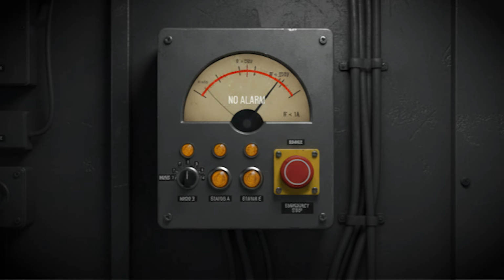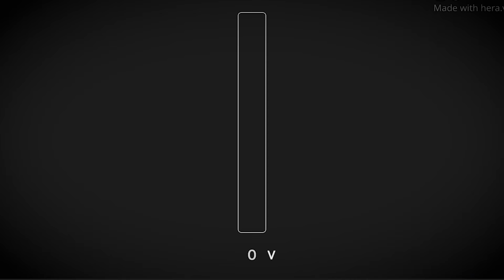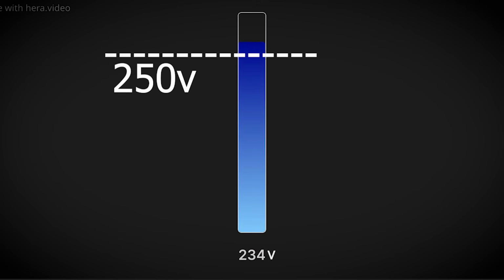Traditionally, meters rely on rigid thresholds. That is, if voltage is greater than 250 volts, raise the alert. If current is less than 1 ampere for 10 minutes or more, log the event.